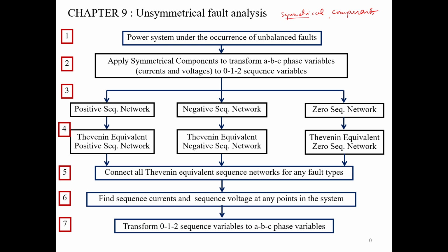The symmetrical component is the tool that we use to transform any unbalanced voltage or current phasors into three sets of balanced V or I phasors.